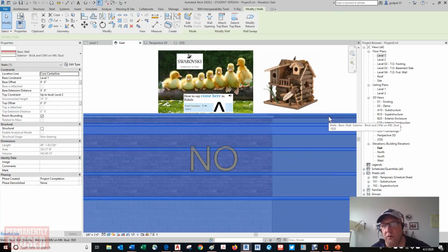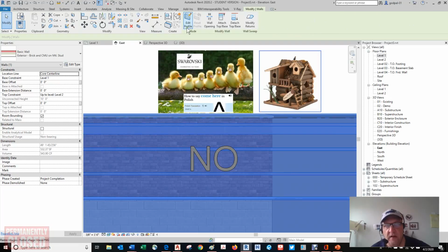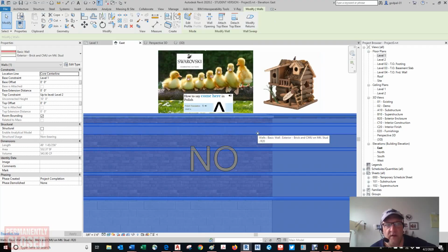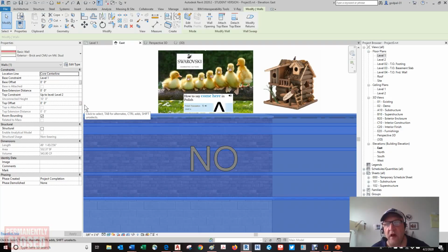So just look, if I select the wall, you'll notice that a contextual tab opens up within the Modify tab on the ribbon, and you'll see that there are 3 panels that opened up containing multiple tools. And the wall now, within the context of drawing it, you could actually change a lot of the parameters, add some parameters to it, and this is the important, powerful aspect of Revit. You can extract embedded data that's built into this object, this elemental object that consists of multiple parts.